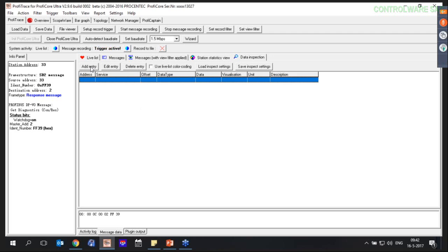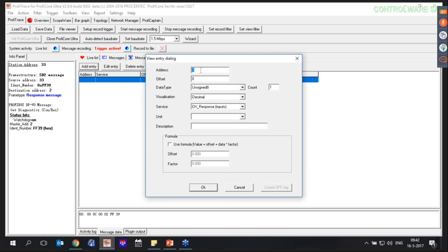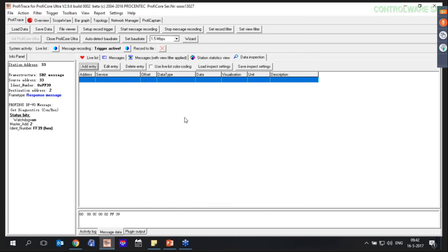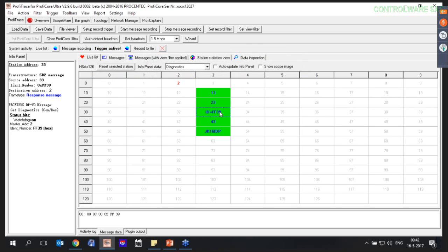I've got an I/O device in front of me. That's a Wago or a Combrix, doesn't matter. And there are LEDs going on and off. So let's see if I can see these outputs. My Wago has address number, let me see. I will switch it off for a moment to see what address it is. Normally it should be in schematics, but it's address number 13.